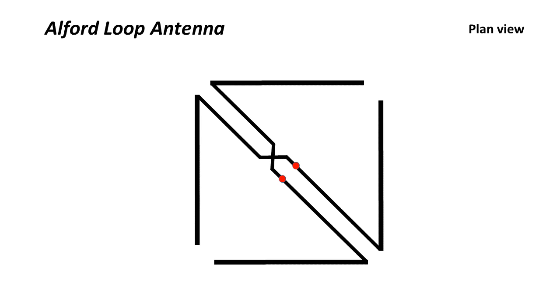We join the two together to get a single feed point and swap over the connections to one antenna to retain the required phase relationship. Now the current distribution in each quarter wave element would look like this, with a current node at the end.